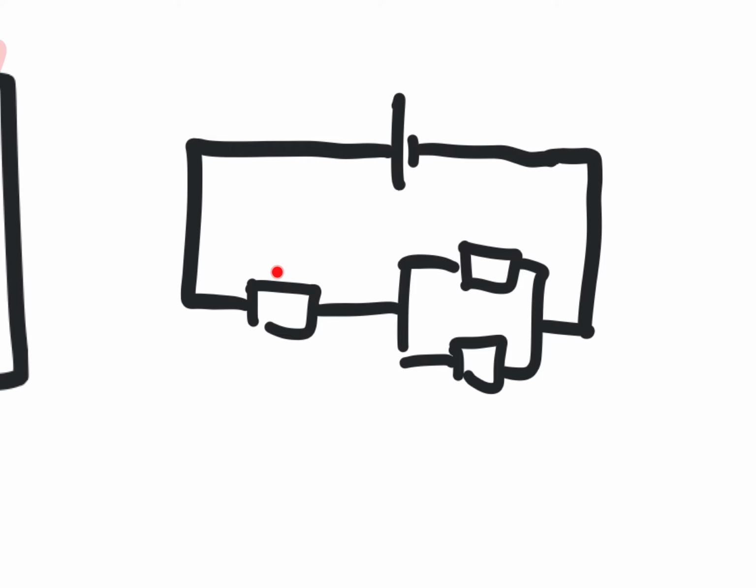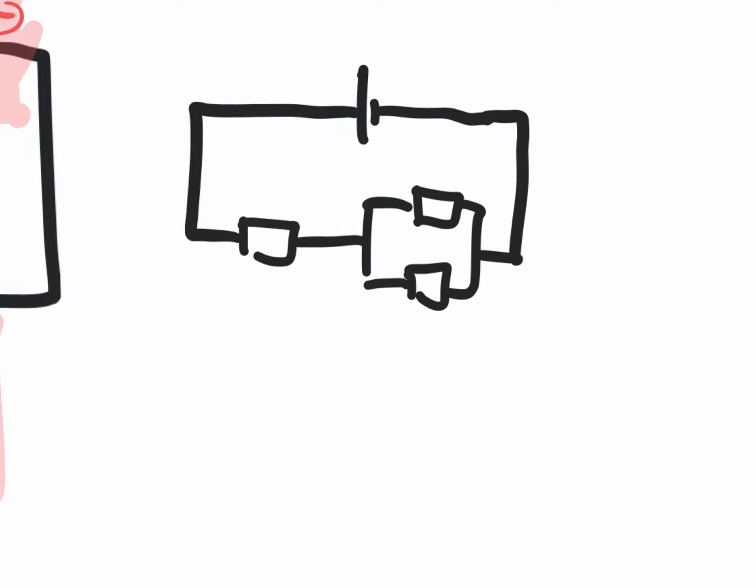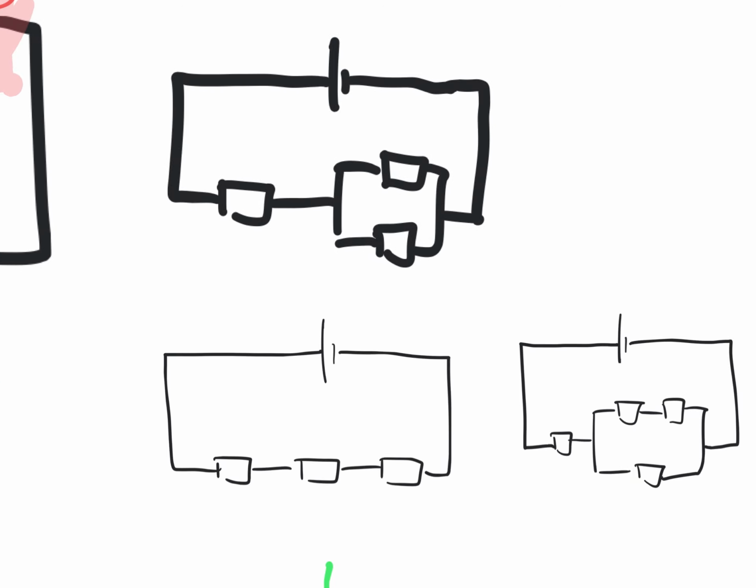So you see over here, there's so many things, right? There's this, there's that. So let's try to simplify as much as possible. What I mean by simplify, maybe let's do this. All right, let's try this over here. So how do I simplify this one over here? Instead of 3 resistors, I want to combine resistors into 1 resistor to make things easier for myself, correct? Now I would tell myself, hey, these are in series. I'm just going to add up these 3 resistors. And when I do add it up, it will become as good as just 1 resistor like that, correct?